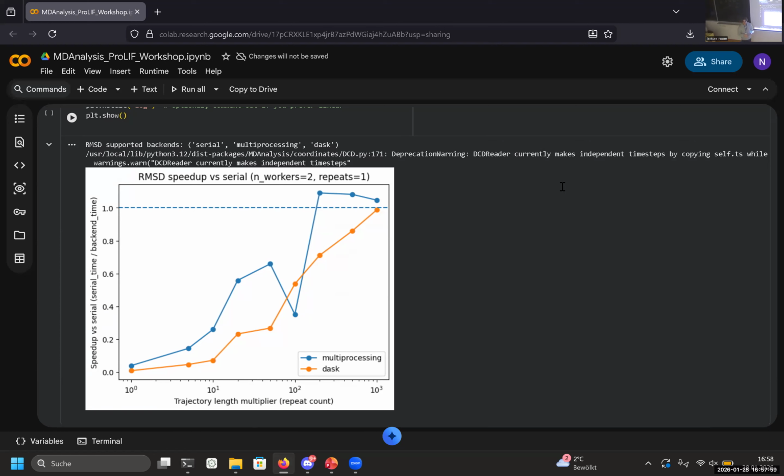While here we start splitting up, doing all of the different distributions, communications of the CPUs with each other, so that it reduces the reason to do that. Which means that multiprocessing with task and multiprocessing is good if you have a bigger trajectory. So if you have a quite big trajectory, or if you know that your analysis takes maybe 20 minutes or 10 minutes, then it is quite reasonable to start parallelizing, or even 5 minutes. But if it only takes like 5 to 10 seconds to run it with a similar CPU, then it's not really beneficial or efficient to start parallelizing, because you then just lose a couple of seconds in the end while doing all of this preparation.